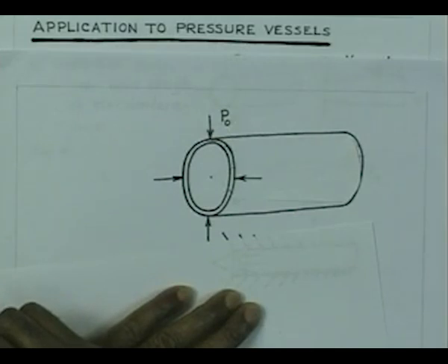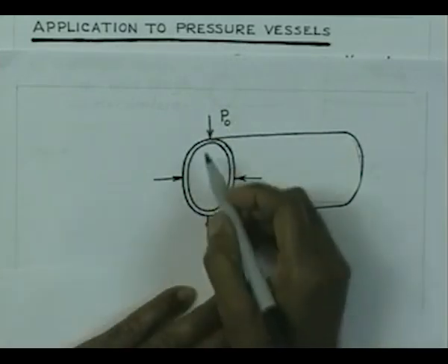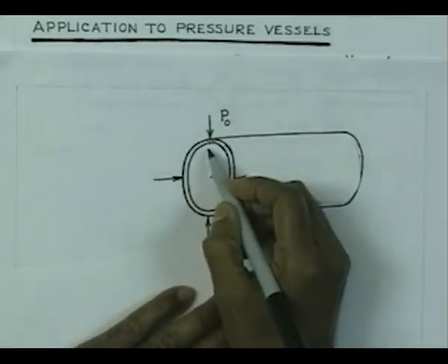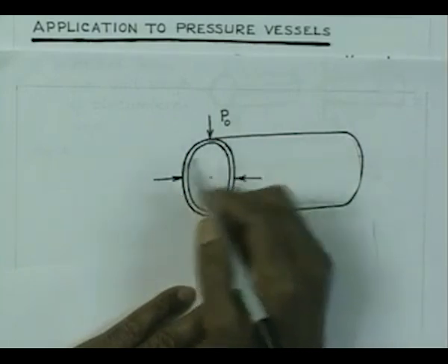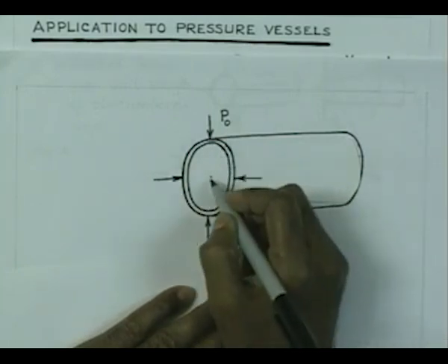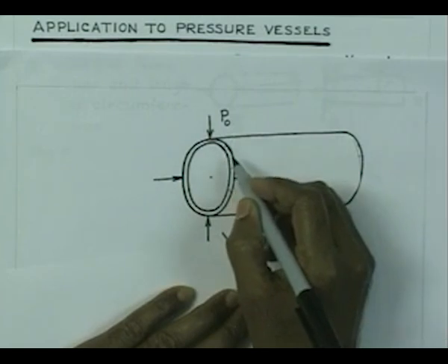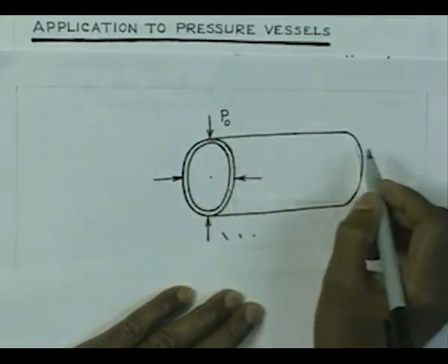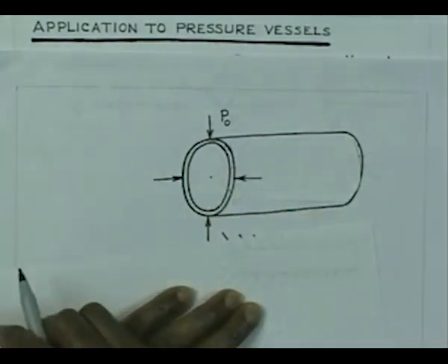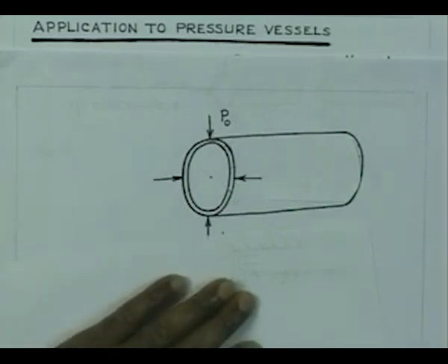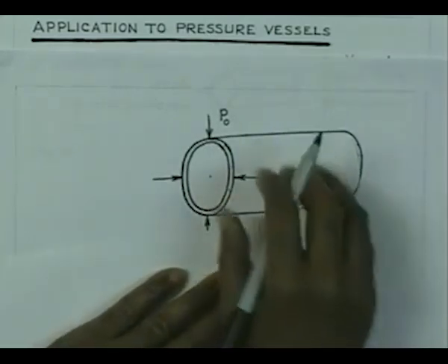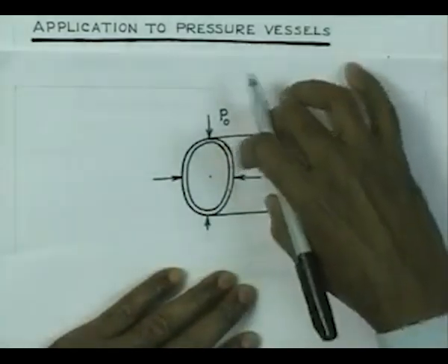If you consider the deformation of this cylinder, obviously you expect that these points will go towards the center and all the points on the circumference at this edge will go close to the center, and that deformation will gradually die as we move away from this edge. Confine your attention to the deformation of a sector.